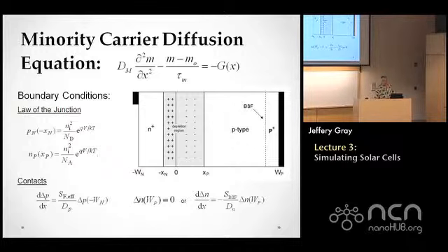So here's the N+ region emitter. We'll assume it's quasi-neutral, and we'll also assume the base is quasi-neutral. For the sake of this discussion, we're going to assume that the depletion region isn't really adding anything to the device, so there's very little recombination or generation going on in the depletion region. And in good solar cells, especially operating at a sufficiently high illumination level or forward bias condition, you can pretty much ignore what's going on in the emitter.